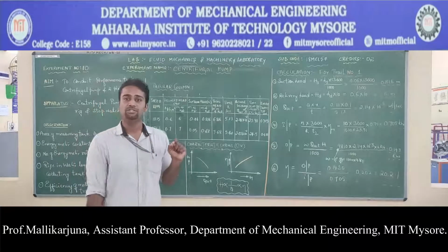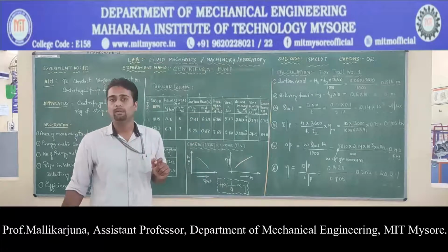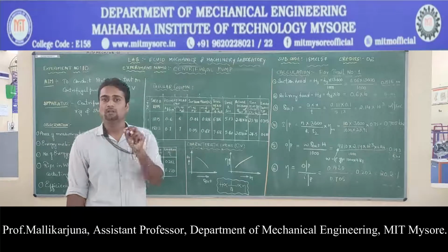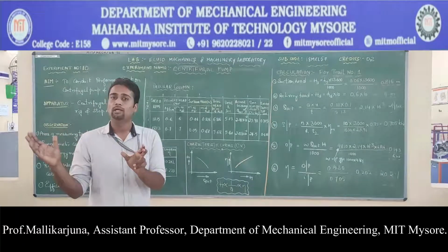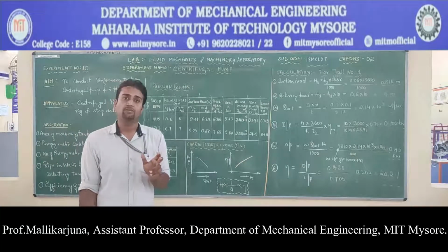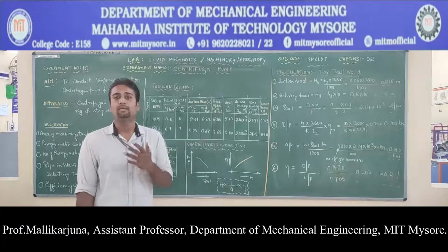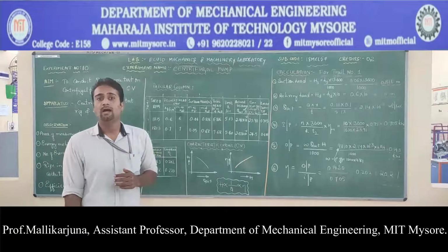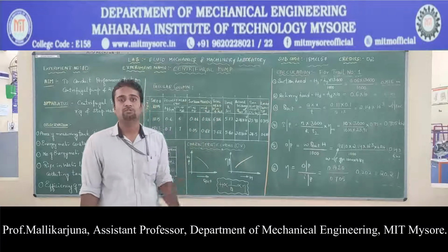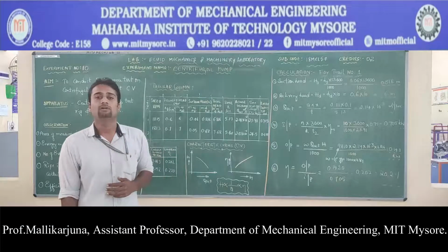So cavitation is nothing but bursting of the bubbles at the various components of the pump because of decrease in pressure below the vapor pressure. The causes or effects are it is going to erode the material, it is going to generate huge noise, and it is going to create the vibration. If you want to avoid it, we have to look for a huge diameter of the eye, I mean impeller. We can run the pumps in parallel and we can look for the level of water on the suction side, which has to be very high. So these are all the procedures for avoiding cavitation.